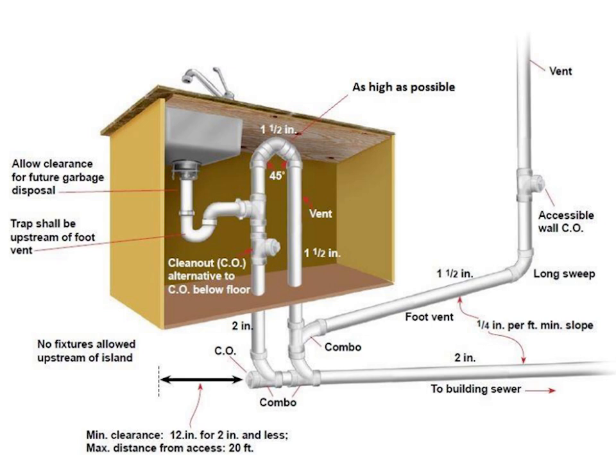So, for an island sink vent, the drain has a vent in back. The vent pipe goes up under the cabinet as high as possible and then hooks back down. It then goes over to the wall and raises up to at least 6 inches above the flood level of the sink. It then joins into the main vent coming from the roof. There's a relief drain on the vent pipe at the low spot, just in case the vent backfills with water. And you have the sink drain pipe 12 to 14 inches from the floor. Minnesota code is listed below.